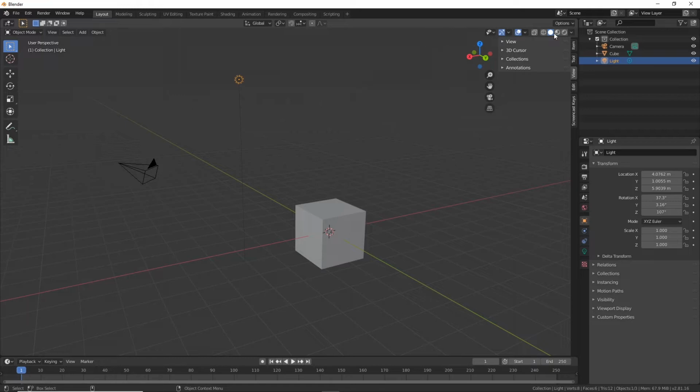Up here in the right, this is all of our Viewport window information. So we've got a tab for view object types, and you can basically hide things using this. So if you ever open up a scene and something's missing or not showing the way you'd want it to, it's probably tabbed off here. And then you've got the show gizmo, which if I toggle that off, notice that it hides the gizmo.